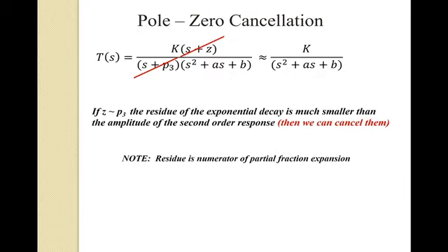Now, as we talk about adding poles and zeros, what we're doing is we're slowly walking you to the position of controller design. How do I build a controller to get a system to do what I want, that has the overshoot that I want, the settling time that I want, basically the response characteristics that I desire for my application. Now, part of this is, hey, if I add a 0 and it can potentially cancel out a pole, what happens? Well, it actually can get to a system where, if I have a third order system and I add a 0 and make it a second order system, if I can truly cancel a pole, that might have some desirable characteristics for what I'm looking to get in my application.